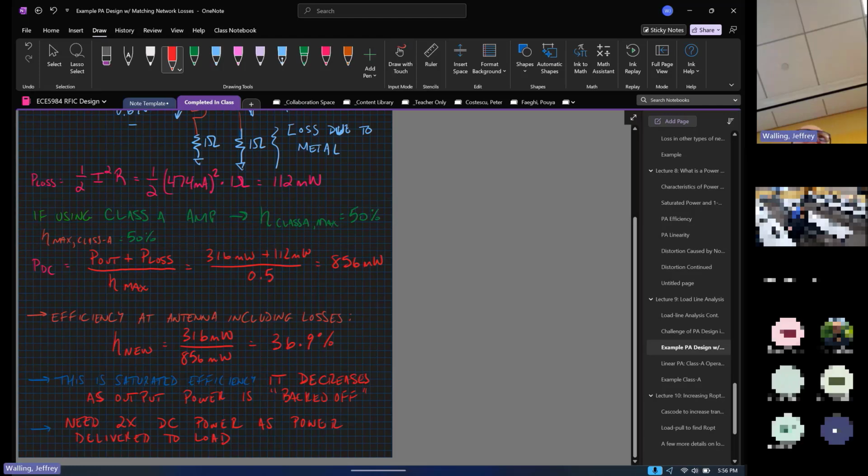How many of you have heard of 3-5 power amplifiers? Anybody know what a 3-5 device is? Gallium nitride. Have you heard of gallium nitride? Gallium arsenide, indium phosphide. Those semiconductors all have what's called a large band gap or a high band gap, at least higher than silicon. That means that they can operate safely from higher voltage levels, even with similar feature sizes. So that's why those devices are typically chosen for RF power amplifiers rather than CMOS. They can work with higher voltages, and it's just a huge advantage.